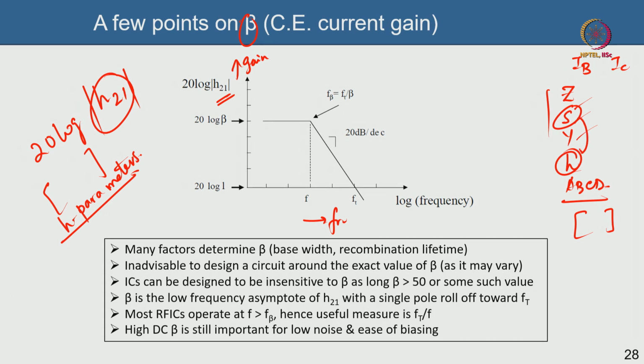However, going from S to H is not very trivial. You have to go to Z parameter, then to Y parameter, then to H parameter. You have to de-embed the parasitics, you have to remove the parasitic component. We will come to that in the subsequent part of the course, but the bottom line here is that the Y axis represents gain, and you can see that gain stays flat at very low frequencies, and then at one point it will start to fall down.